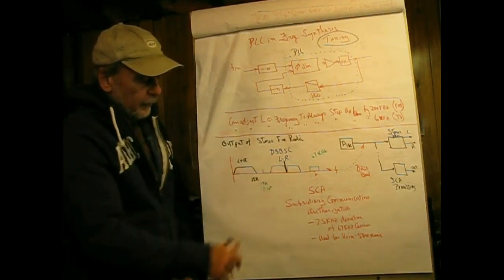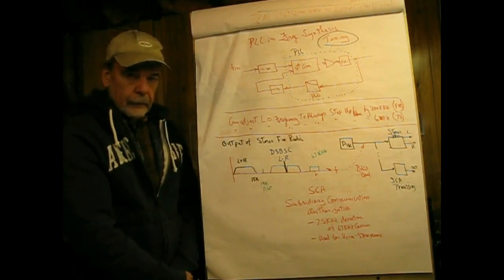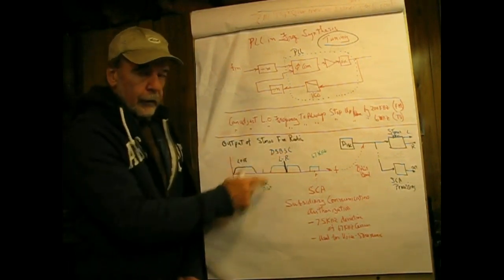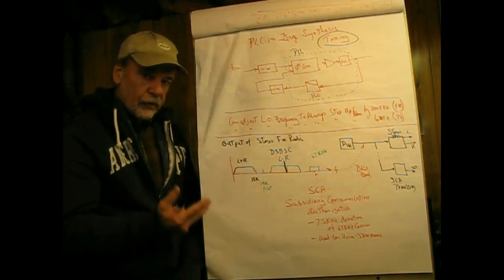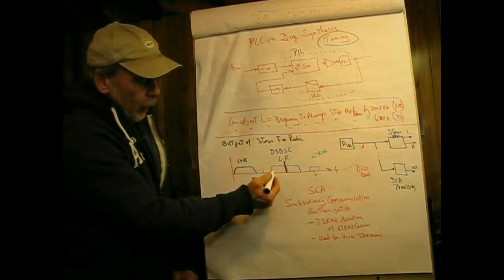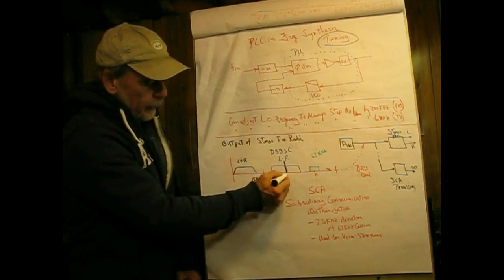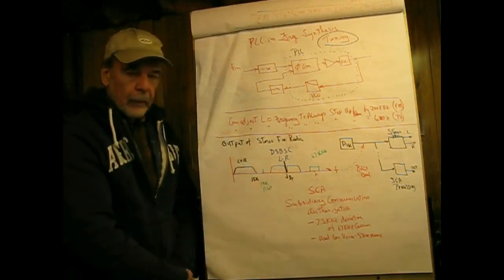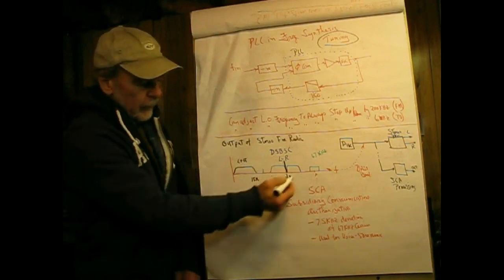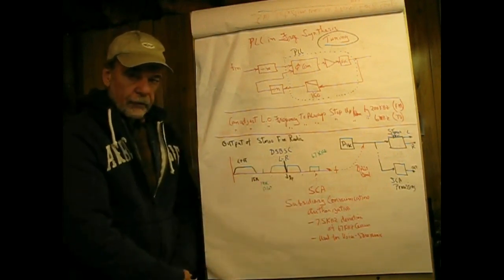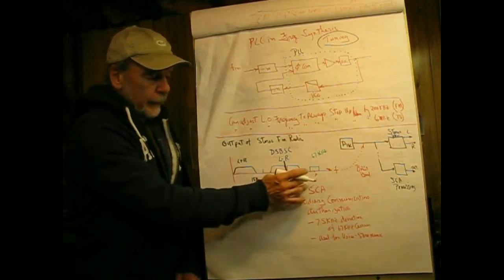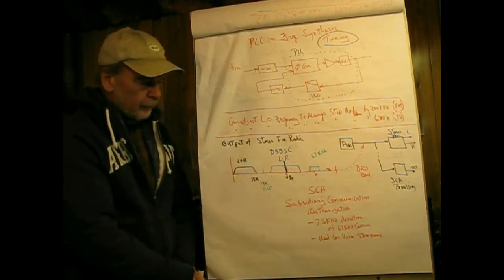Now, sitting up above that is a left minus right, suppressed double sideband suppressed carrier AM signal. The center of this is 38 kilohertz, and this is going to be 38 kilohertz minus 15K, and 38 kilohertz plus 15K. So here we've got our high fidelity embedded right into the system.